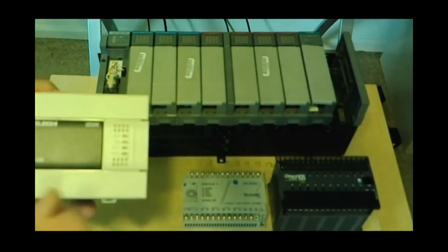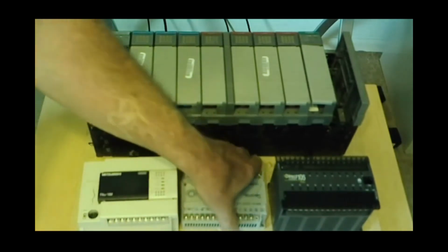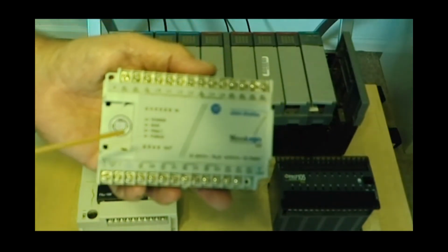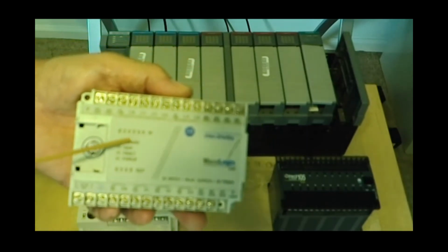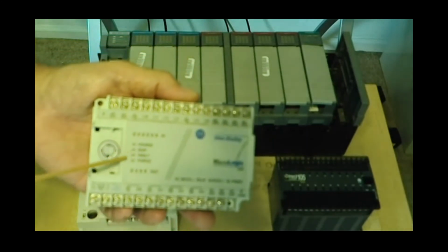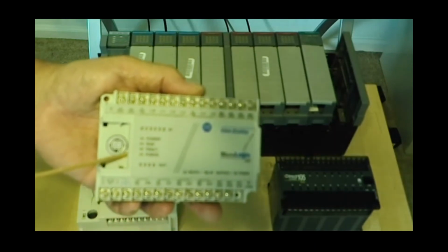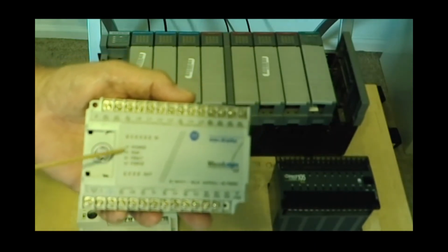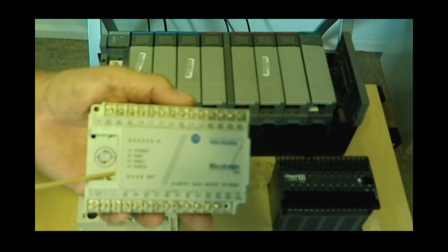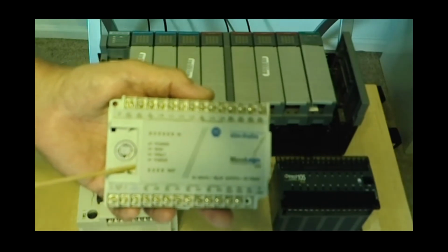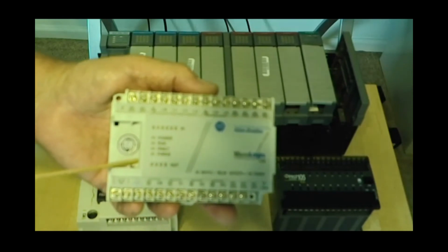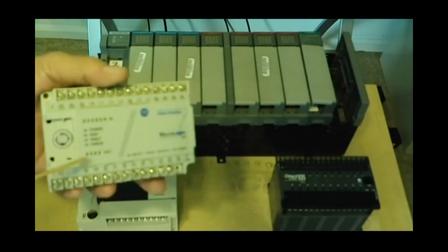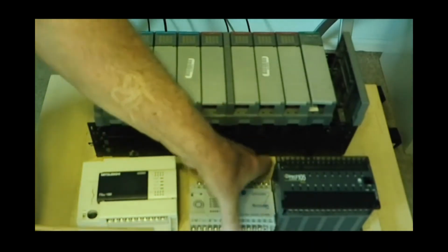So with any PLC, regardless which brand you run into or use, if you're going to have to troubleshoot a CPU, you're going to need the paperwork, the manuals that come with the CPU, or download the PDFs. And that will give you what the error codes actually mean, because no two error codes are going to be the same. All makes, manufacturers, and models have different error codes. And this applies to every PLC.